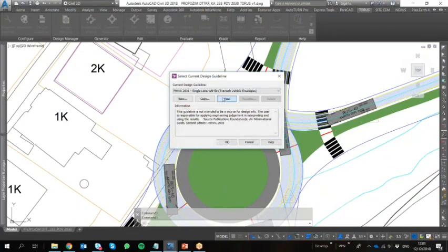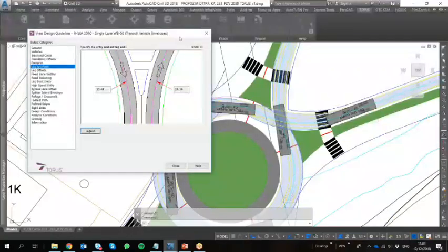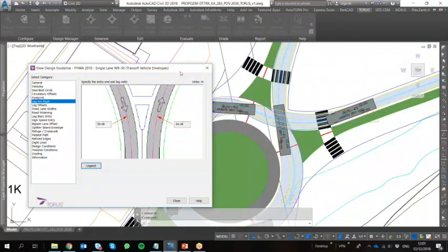So when we generate vehicle movements and we generate a roundabout leg, what we do is that we define the path, how the vehicle enters the roundabout and how it exits. We don't define the curb edge. We don't say that this is going to be a 20-meter arc radius curb.